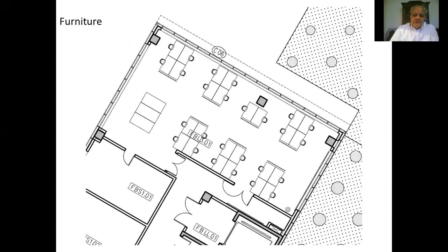The second plan, you see, we are using the same architectural plan that we developed in the beginning. That's why when we use AutoCAD or any system, we need to have layers. We don't put everything on the same layer. We have a layer for center lines, a layer for columns, a layer for doors, a layer for windows, so we can turn these layers on and off easily. We will discuss more about that in the construction documents lecture.